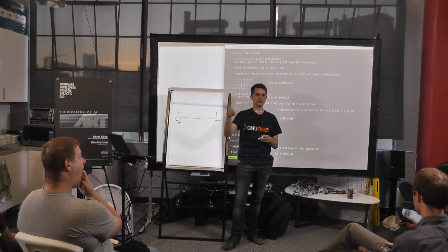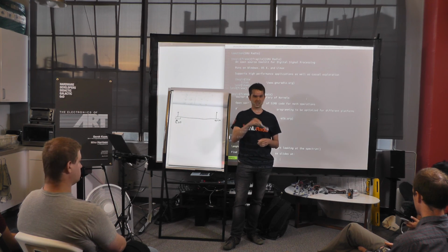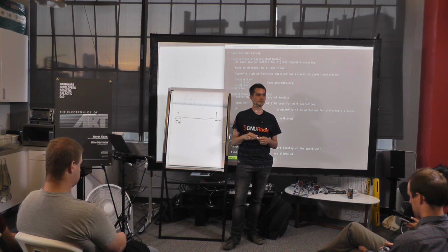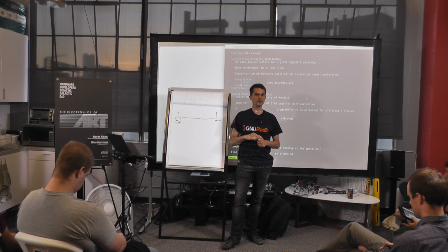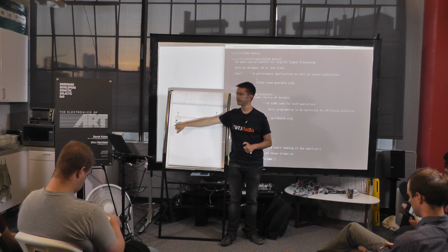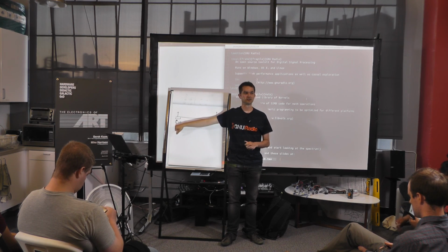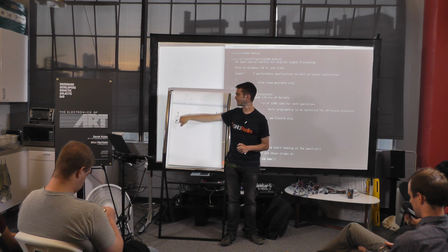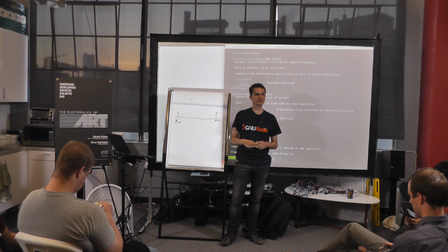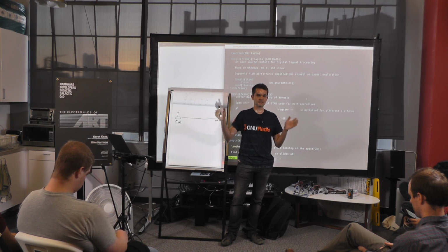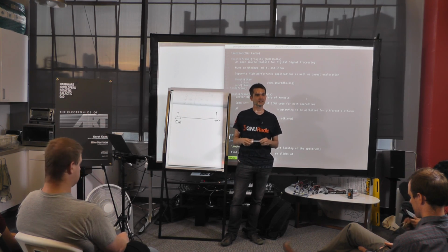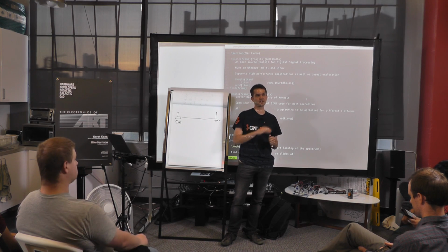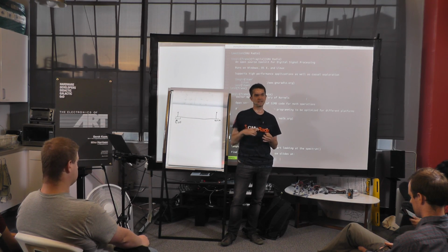There's an opportunity there for you to implement custom code onto any one of those and do some signal processing there. But fundamentally, what you end up doing is just getting an analog to digital conversion at your sample rate of this baseband signal. And that could contain the actual information carried there, could be anything. And then you implement all of the logic for demodulating the AM, the FM, the Iridium in software.